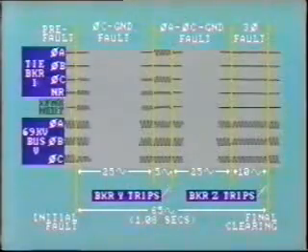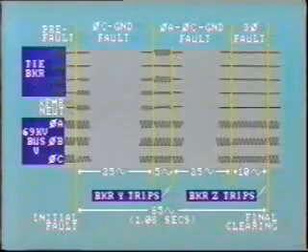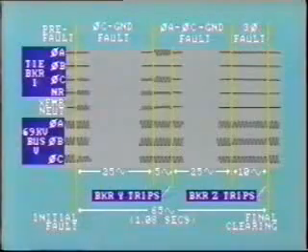The oscillograph has recorded 69 kV bus voltages in all 3 phases, neutral current in a grounding transformer, and current in the bus tie breaker, all 3 phases as well as the residual current. The total elapsed time between the initial fault and final breaker clearing was 65 cycles, just over 1 second. Notice that we have broken the traces to indicate where the waveforms just repeat themselves.